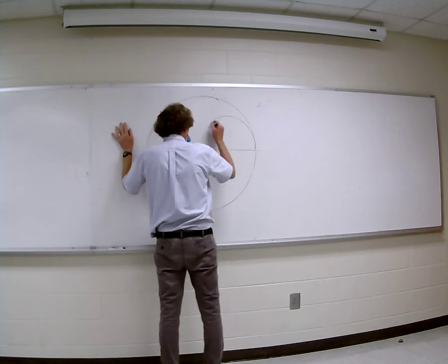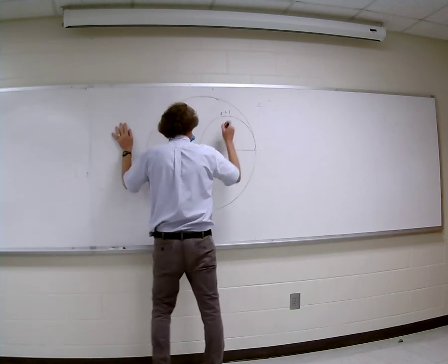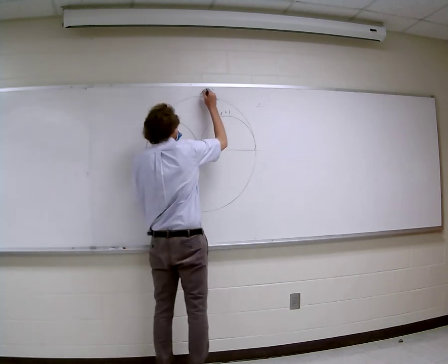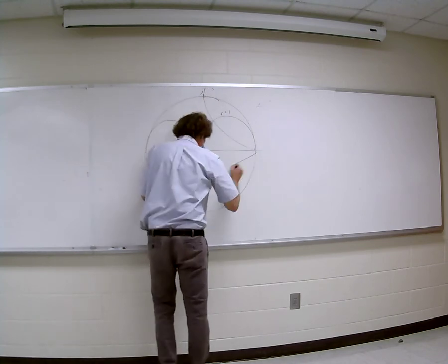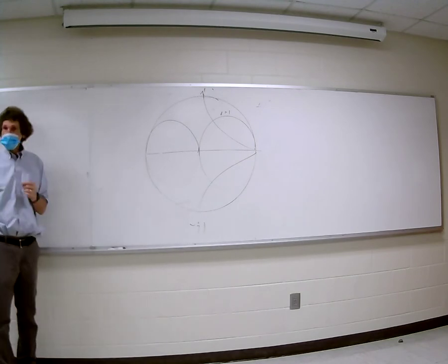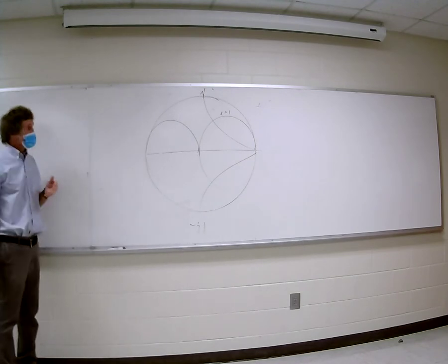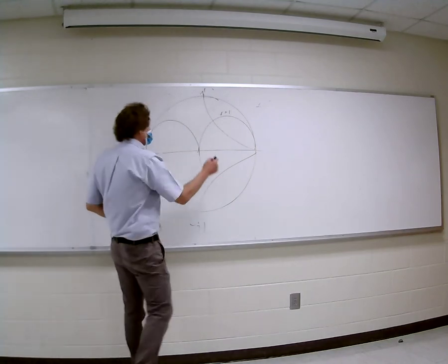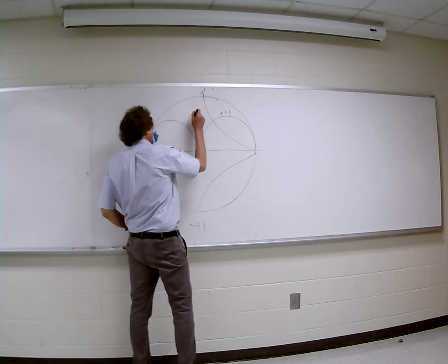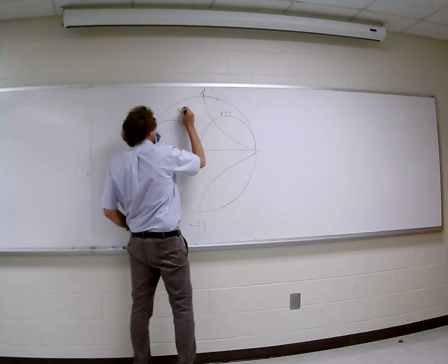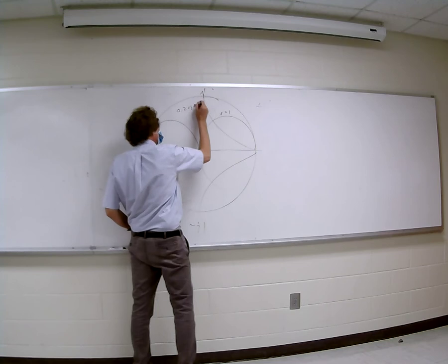This is the one circle here, and this is the rotated circle here. And we know J1 is here, right? This would be minus J1. You all know about that, right? This is a standard Smith chart. So now we're going to look at what happens if we're outside the rotated and the original R1 circle. Suppose we're here. Find me a point here that's normalized 0.2 plus J 0.8. Yes.